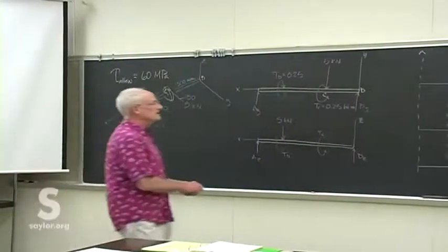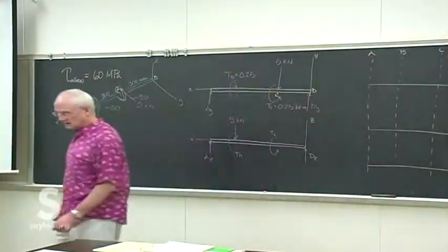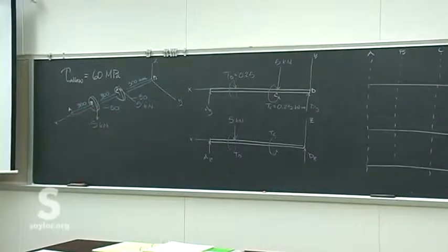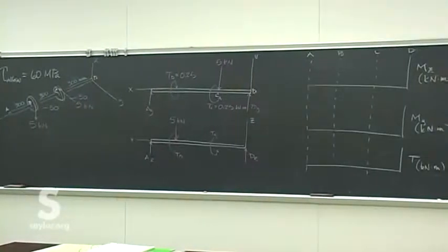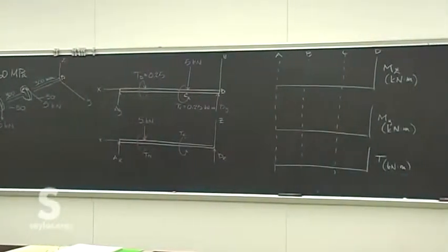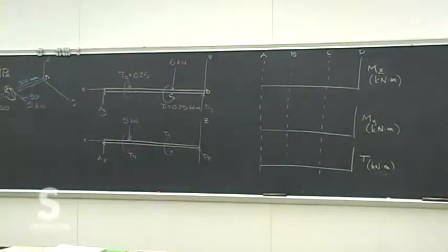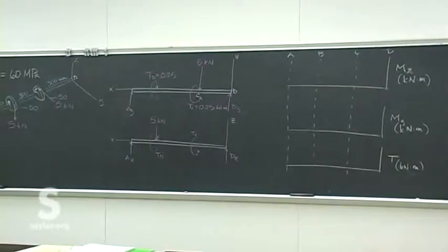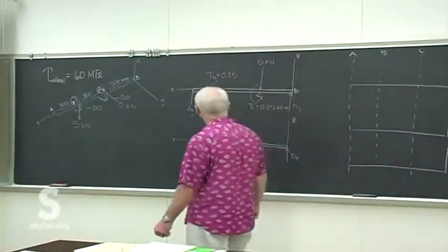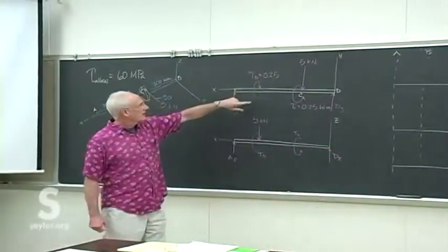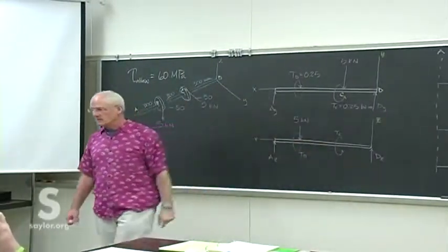Okay, so come up with these drawings here where we show the torque, the moment at different places. I think it's a little easier making them above and below each other. Just a little bit less chance of making errors. Remember, for the moment diagrams, the torsions don't apply, and then for the torsion diagram, the moments don't apply.